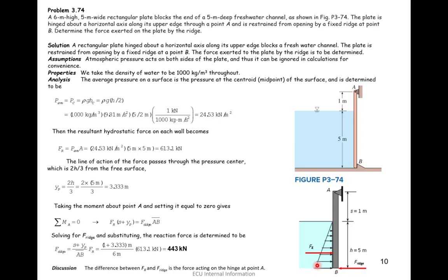So first we need to work out what the hydrostatic pressure force is, which in this case has been shown. Then for working out the hydrostatic pressure, we need to know what the centroid of this plate is, which is obviously rectangular, and we know. Then we can easily work out what hc is, which would be half of that. Remember, it is where the centroid would be from the surface of the liquid, not the centroid of the whole surface, because it is partially submerged in water.